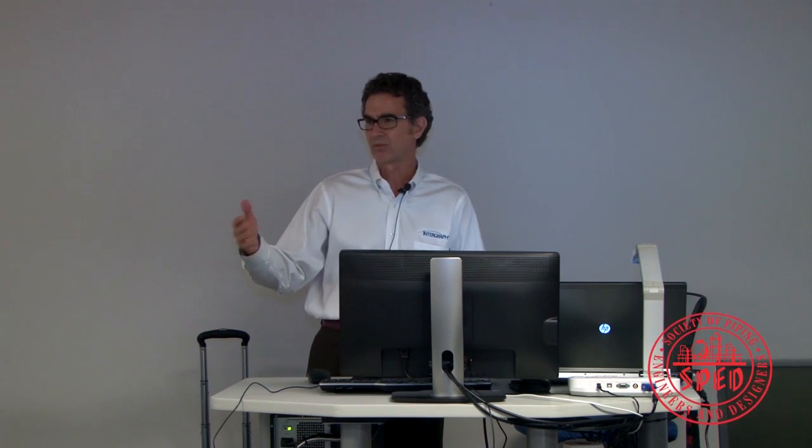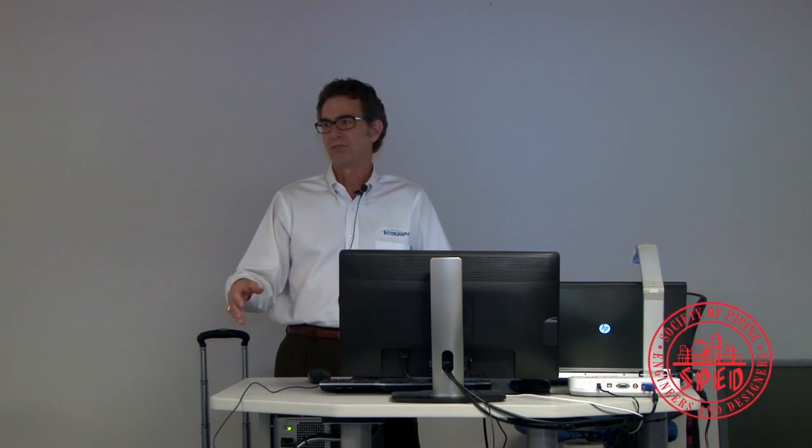So the workflow is that the designer will develop the drawings, and they'll have a critical line list, and this critical line list will identify which layouts have to be analyzed for safety or for load on equipment. And then those drawings go over the wall to the engineering side, and they use a program like CESAR 2. So this is that CESAR 2 side.